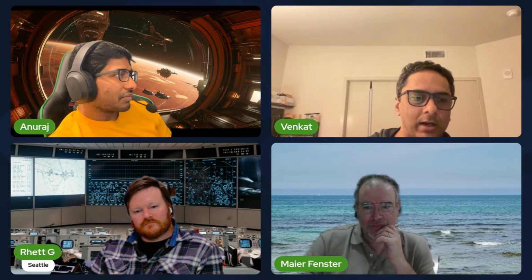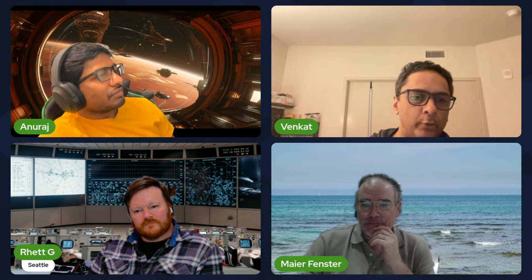This way you can turn off the RPi when power is low and just work with the hat. You'd have to independently power the hat, but yeah, it could work in low power mode and still have connectivity. The RPi is going to pull a lot more power than that. Okay. So even with Wi-Fi, I guess. Yeah. All right. I'm just trying to get the logic straight. So the motivating reason for RPi plus ESP32 hat is low power Wi-Fi connectivity. Is this a good reason? Okay.